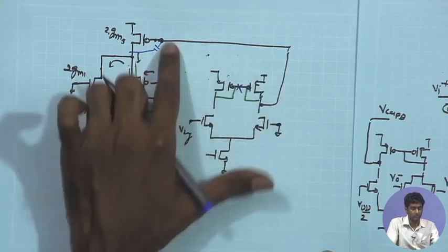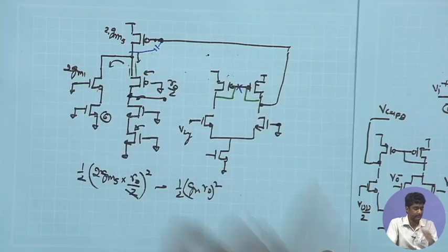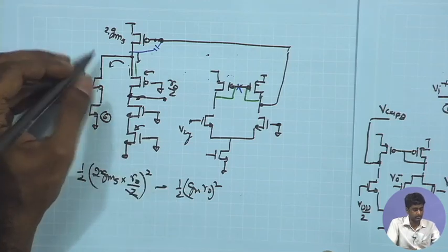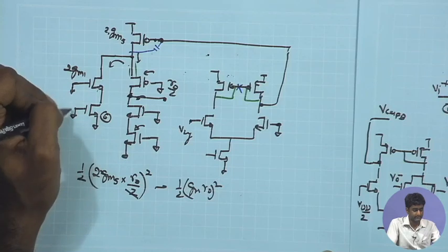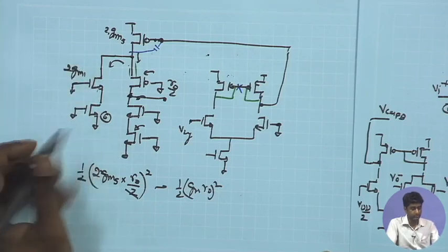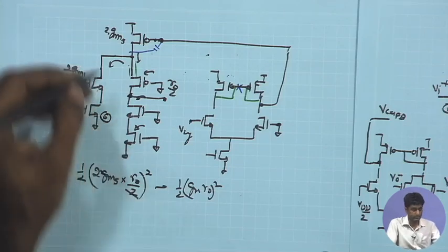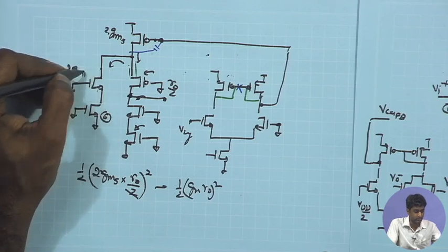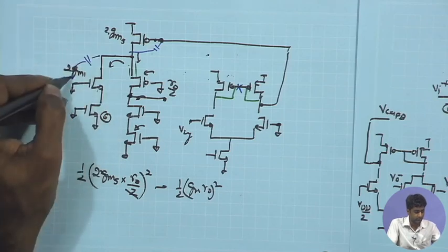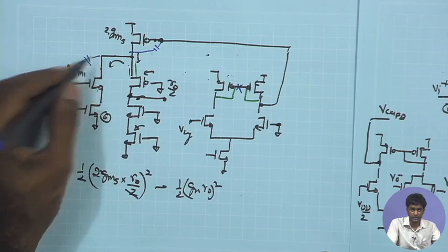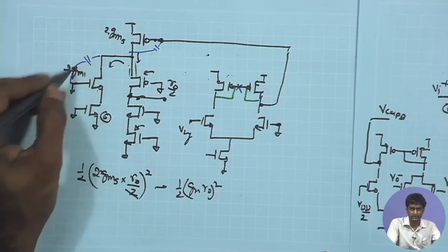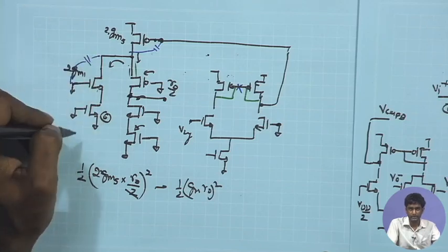So at least for the common mode feedback loop, what we can see is it is going to introduce a sufficient Miller multiplication. The other transistors, gate is AC ground, here also gate is AC ground. So if I look at the parasitic capacitance component, if I just try to draw and understand which one is going to be the dominant one, the CGD of this MOSFET, gate is grounded, therefore the CGD of this MOSFET is going to appear as it is.